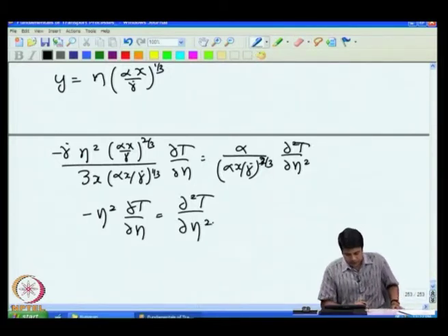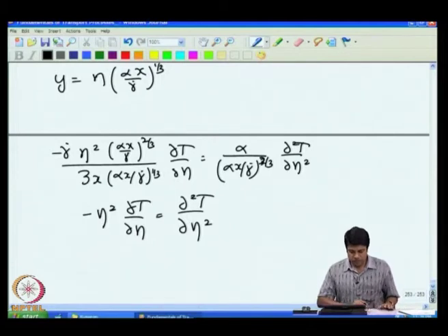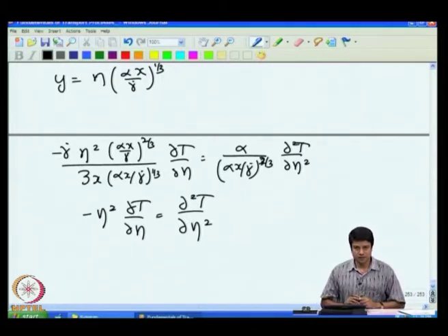Okay. So, this then is the final solution for the equation in terms of eta. As we had expected, if we scaled the y coordinate by that length L, which is based upon the x distance, the distance from the upstream edge, then you will finally end up with a solution in which it does not individually depend upon x, y, gamma dot and alpha.